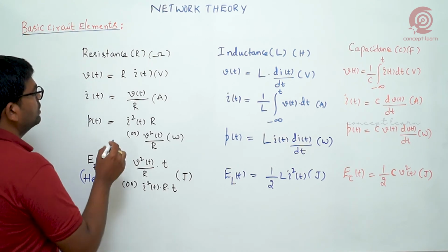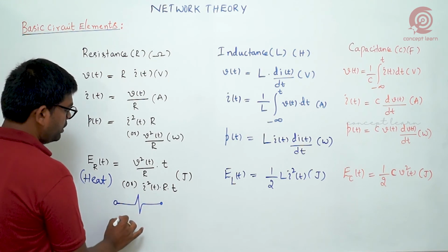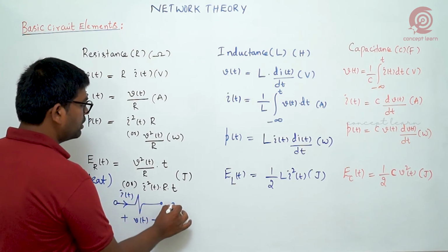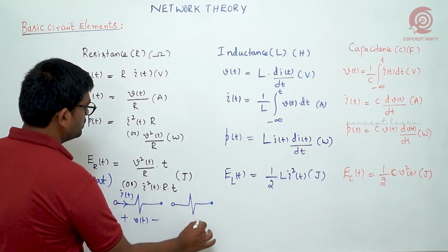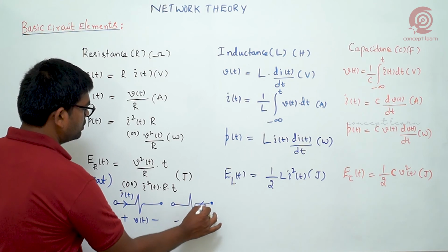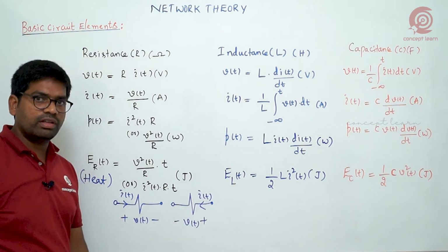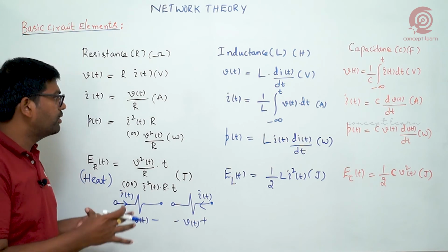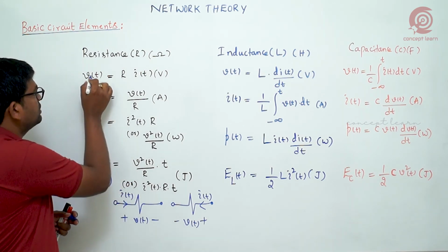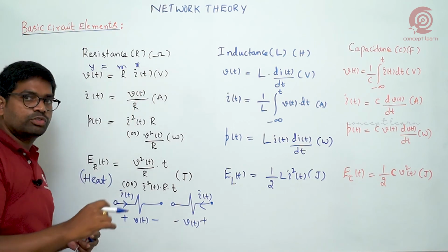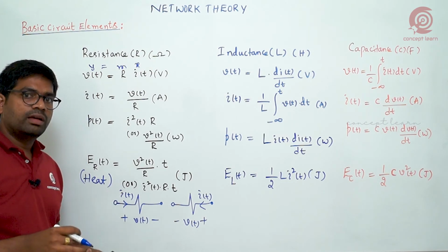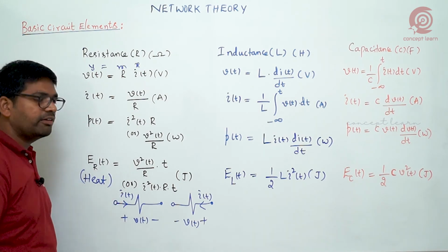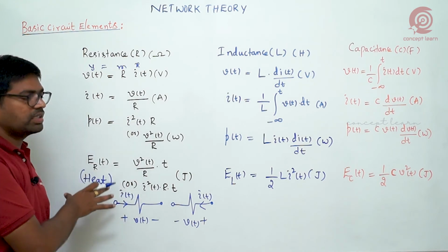How did we indicate resistance here? In this fashion. If you give voltage in this way, this will be the current direction, but you can even give the current or the voltage in the opposite manner also. Absolutely there is no change in behavior. So for this reason we name resistance a bilateral element. Basically resistance is passive, and the V-I characteristic is like y equals mx plus c, a straight line passing through the origin, so it is a linear element. So it is a passive, linear, bilateral element, but it is dissipating energy in the form of heat. These are the major relations for the resistance part.